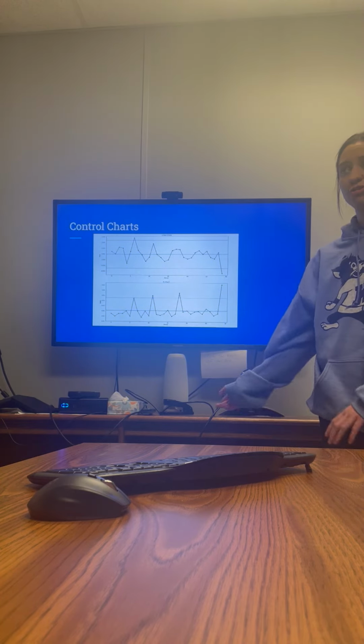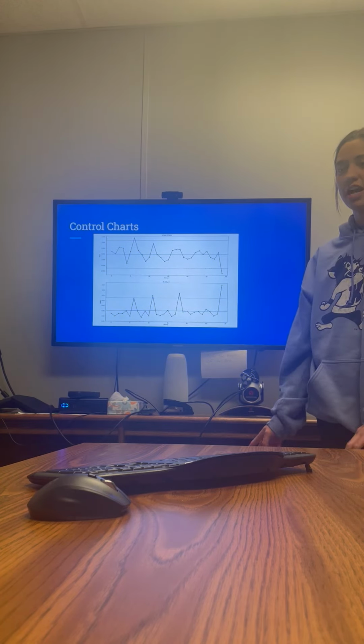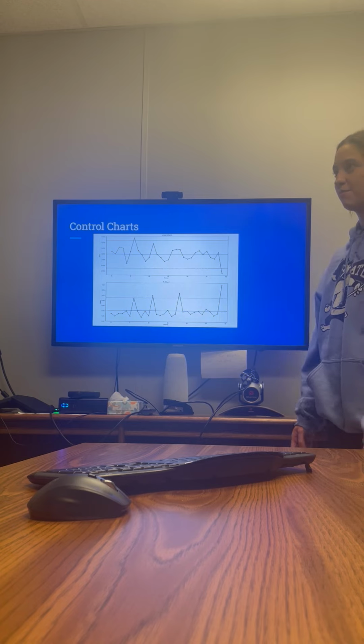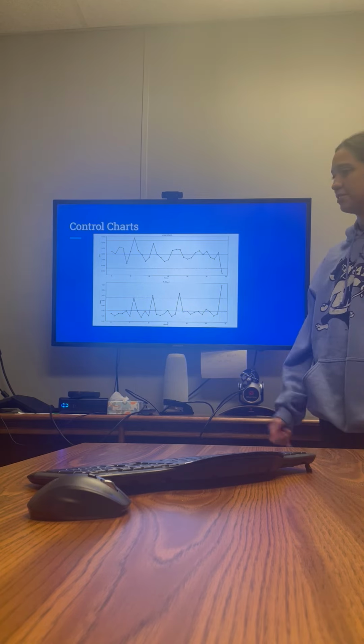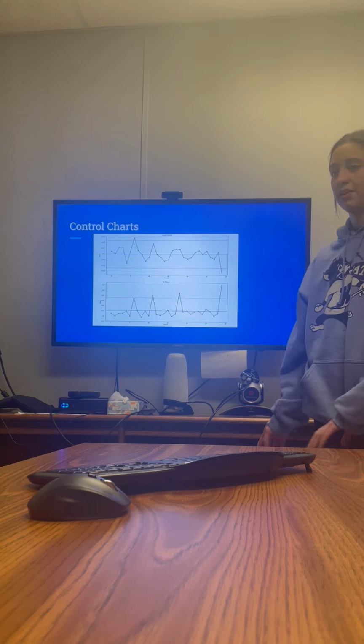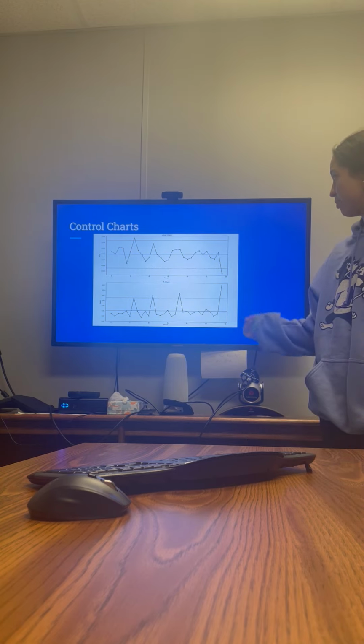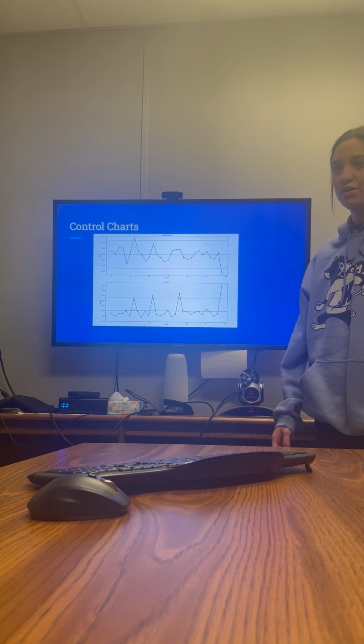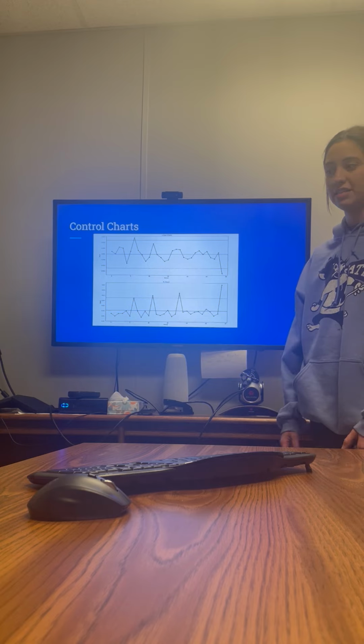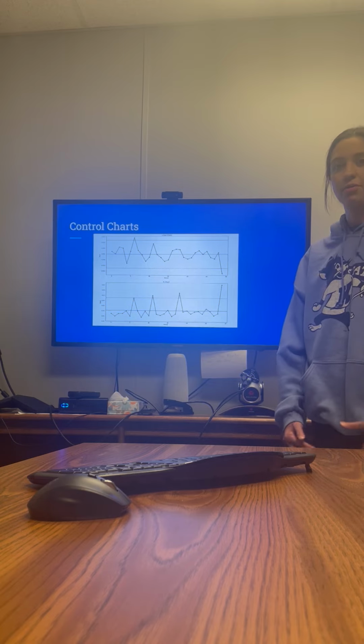For our control charts, we used an X-bar and R chart. And from the data that we collected using the SPC design being implemented on the production floor line, we got a couple points out of the control limits, which then represents that the process is out of control and the variability is high and needs to be redesigned to control the whole process.